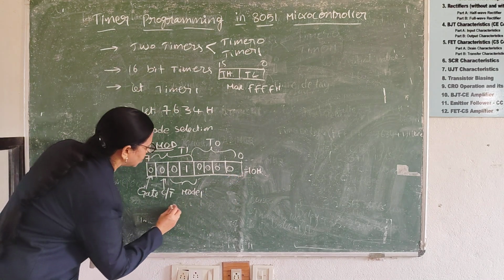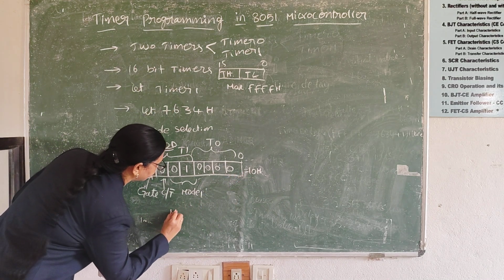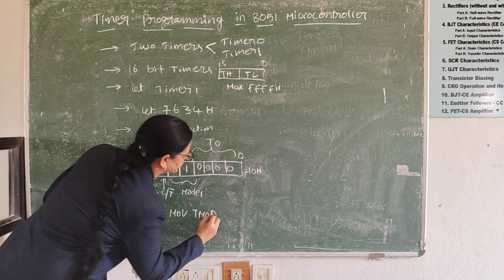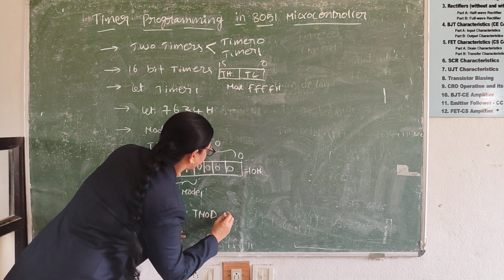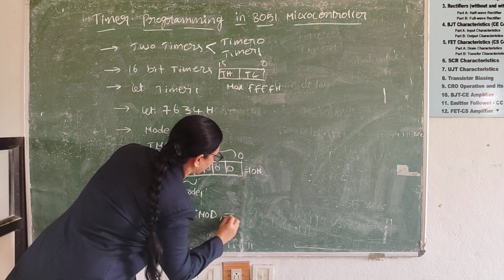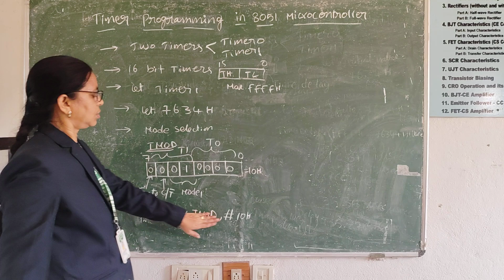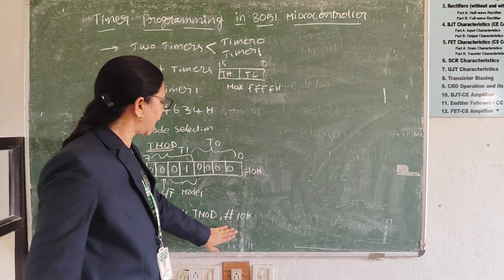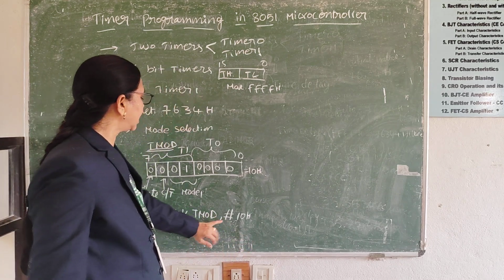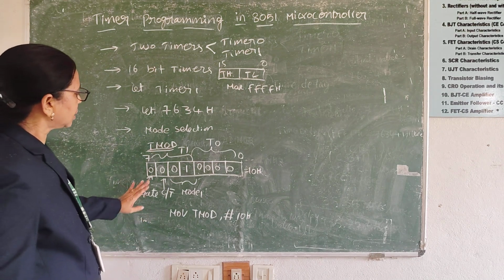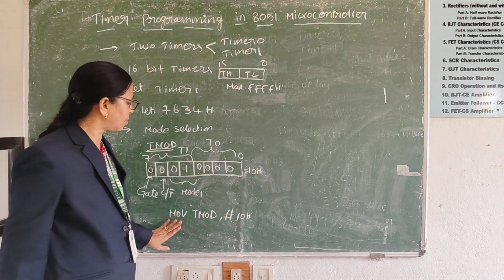The command used for this is MOV TMOD, #10H. We write the hash because it represents data.